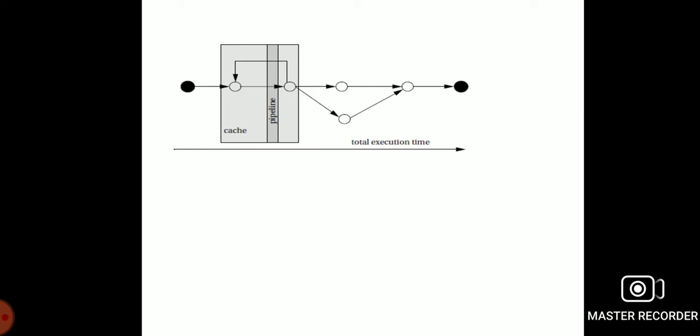The length of the program that can be measured is limited by the accuracy of the timer. Now, the logic analyzer measures the start and stop time of the code segment. The length of the code that can be measured is limited by the size of the logic analyzer buffer.